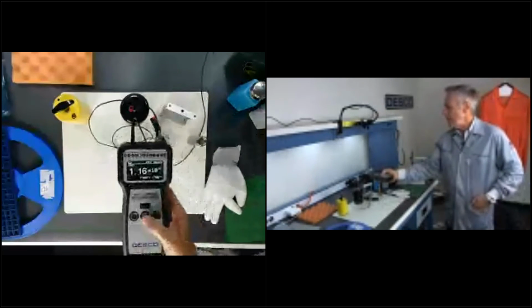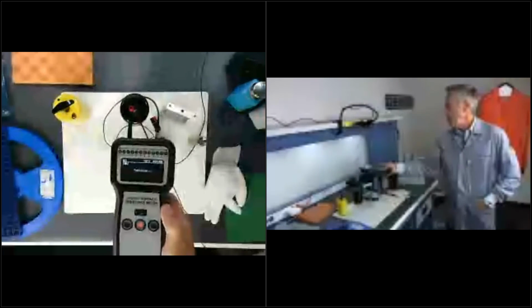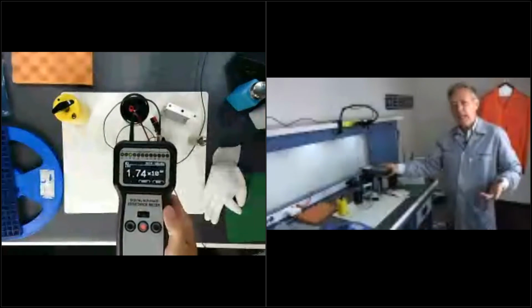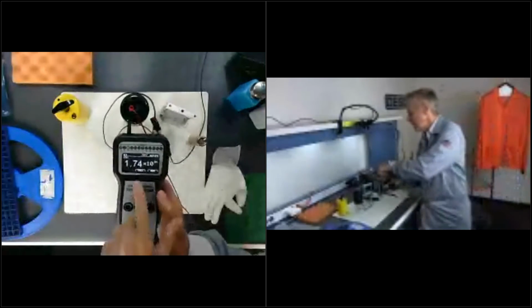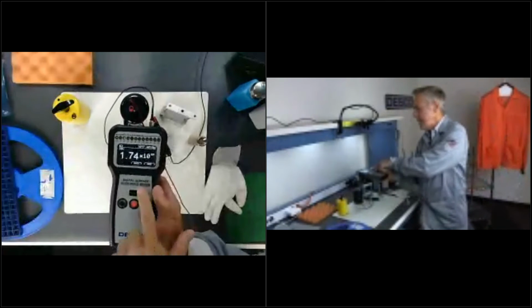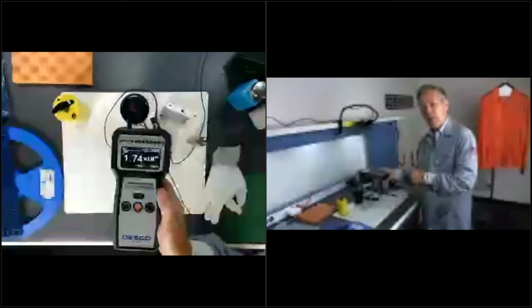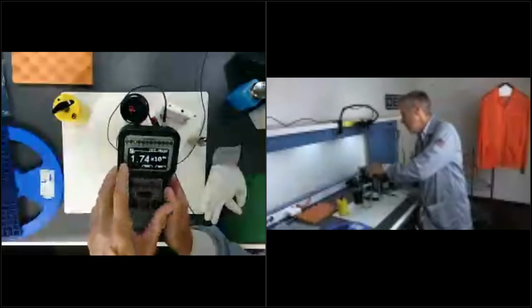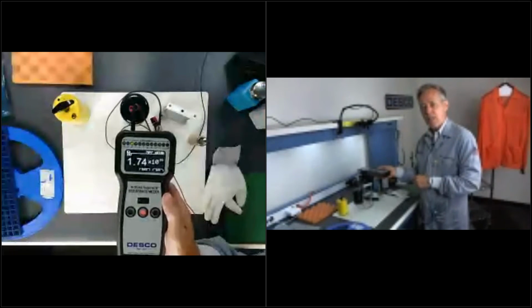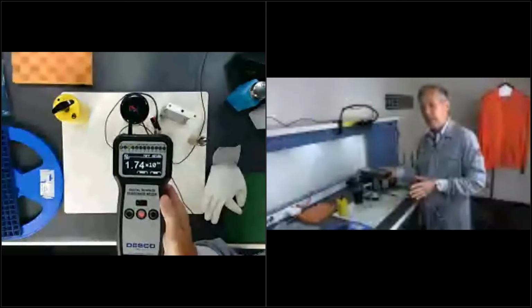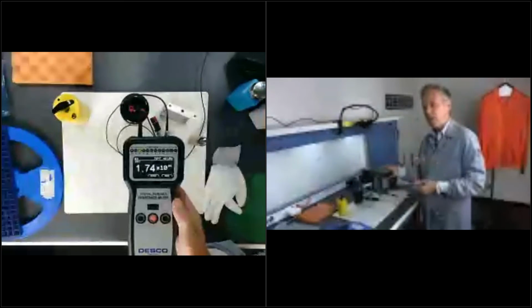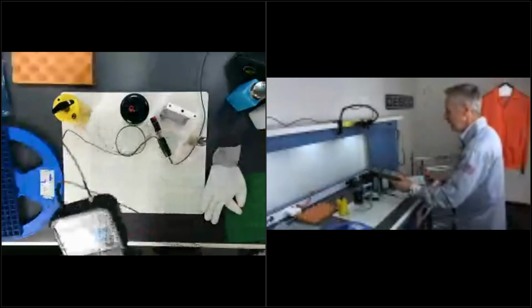So again, I'm going to run my measurement on the floor, and a floor should be less than 1 × 10⁹. You can see that this is a conductive floor, 10⁴. That measurement came up very fast. You'll also notice that it switched to 10 volts. So that's an important thing. This meter is doing everything you need to do for you, making your life a whole lot easier.